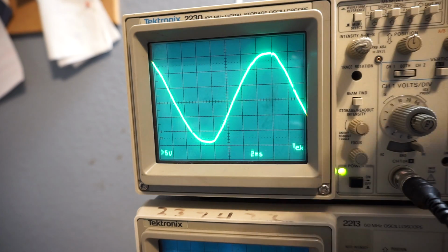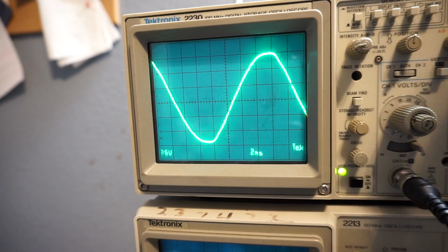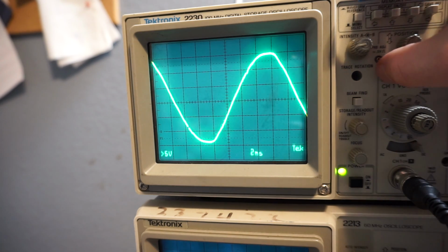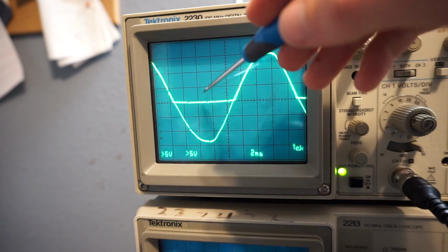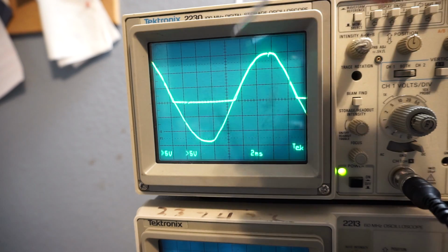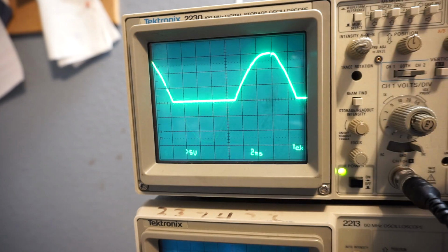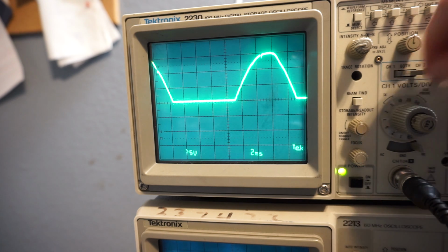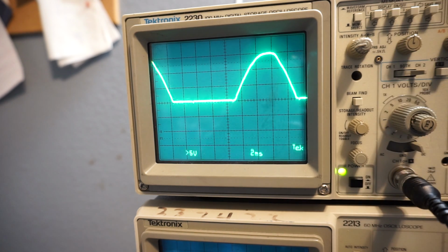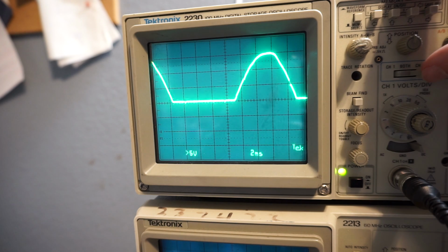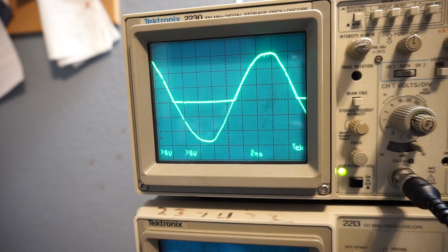Alright guys, so I want to show you this on the oscilloscope. Here's the actual AC waveform coming out of the transformer, right? And if I flip this guy over, you can see both waves. You can see that the actual output of the SCR through the load is chopped off. It's only giving that positive half of the cycle. So that's what the SCR looks like, just like the diode, right? There's nothing fancy going on there. It looks just like we saw in the diode. But here's the cool thing.